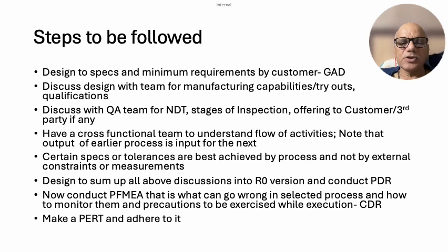When the first article gets produced, the inspection report of the first article goes into the CDR, the critical design review, and if we are getting all the requirements meeting the specs and codes and the customer and end users' expectations, then the CDR is also approved.